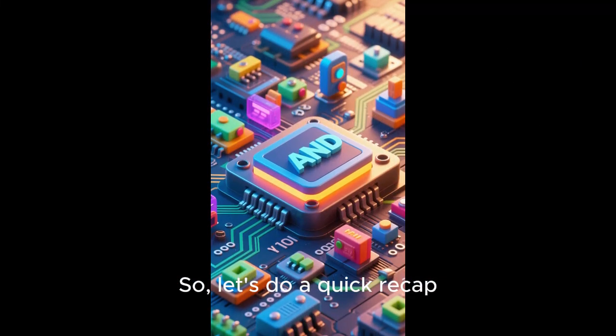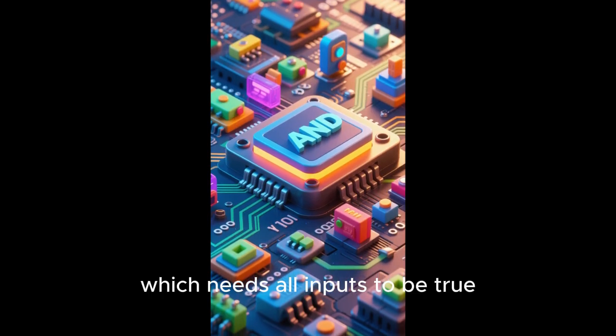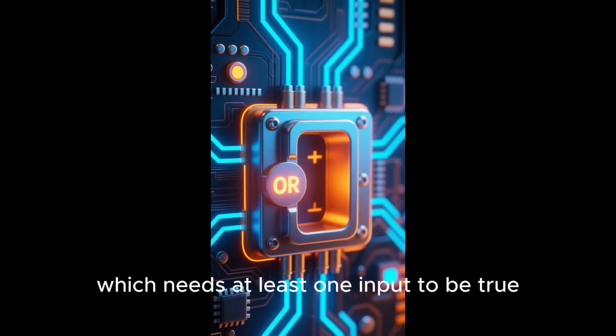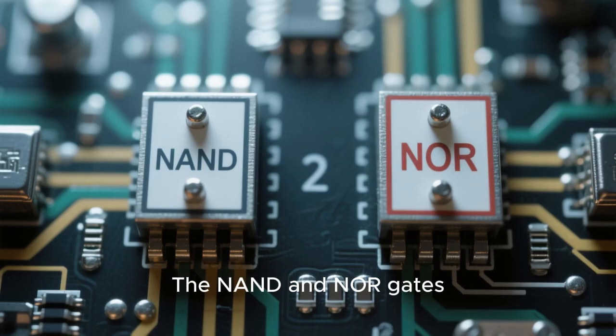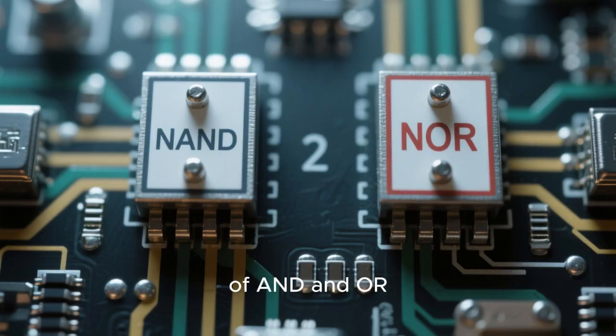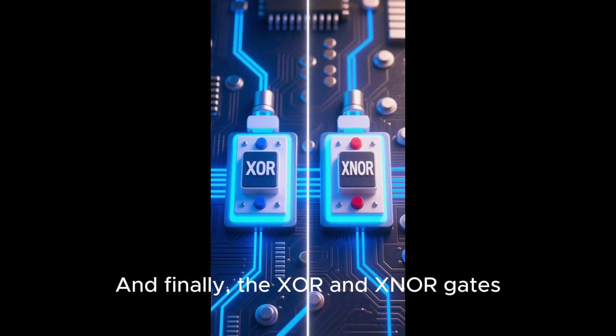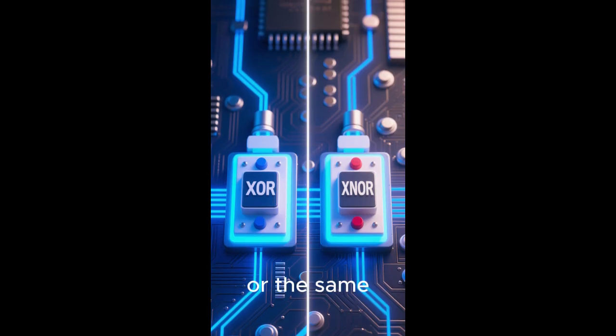So, let's do a quick recap. We have the AND gate, which needs all inputs to be true. The OR gate, which needs at least one input to be true. The NOT gate, which flips the input. The NAND and NOR gates, which are universal and are the opposites of AND and OR. And finally, the XOR and XNOR gates, which check if inputs are different or the same.